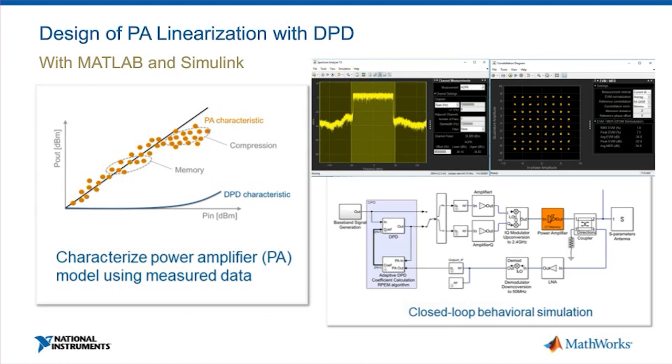So for high bandwidth, we are dealing with the problem of nonlinearity. Maintaining a linear power amplifier profile across the range and across the frequency is very difficult. Power amplifiers will drift at higher input levels and everything will be destroyed because you have harmonics, you have all kinds of nonlinearity effects. So no design that requires large bandwidth is complete without taking your power amplifiers and trying to correct for the nonlinearity with your digital pre-distortion.